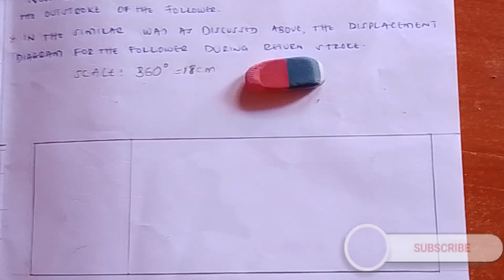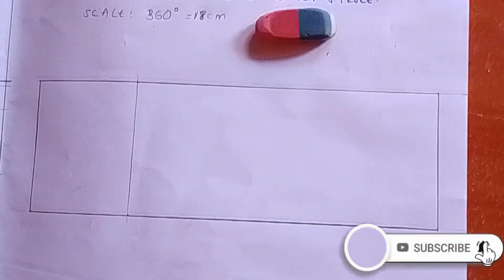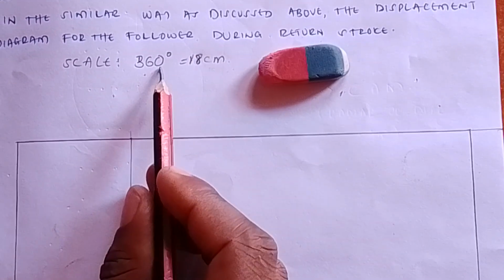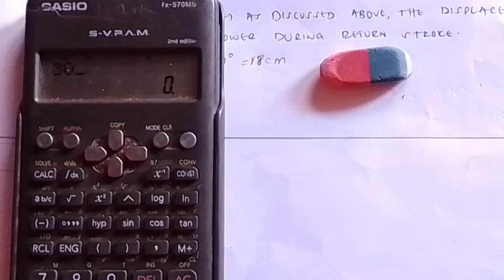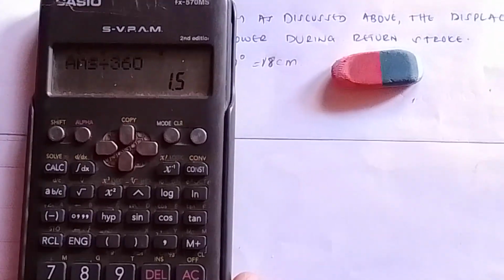Again, we have been told there is a dwell. Let us say the dwell is 30 degrees. From this point, you'll be told there is a dwell of the cam, which is 30 degrees. Again, using your scale, 360 degrees equals 18 centimeters. What about 30 degrees? You take your calculator and say 30 times 18, then divided by 360. We are converting the degrees into centimeters.